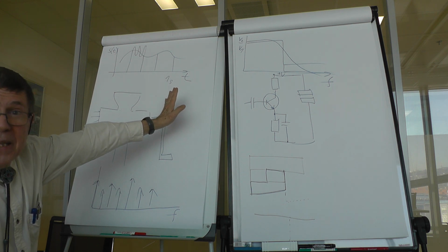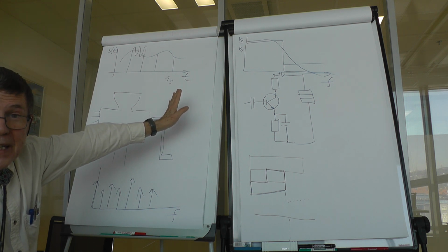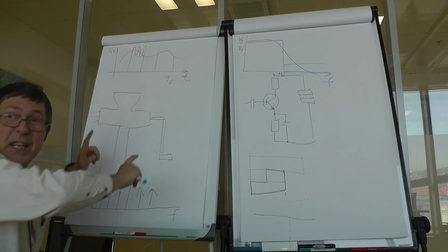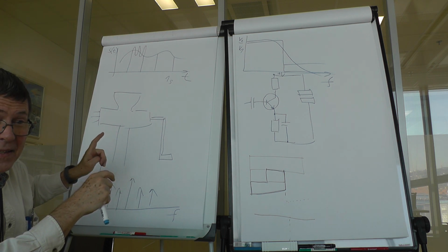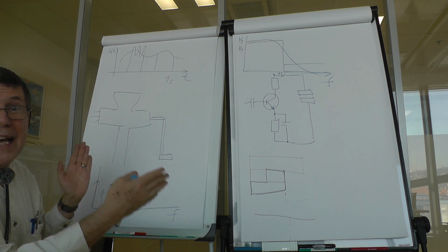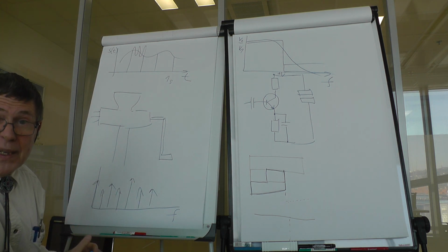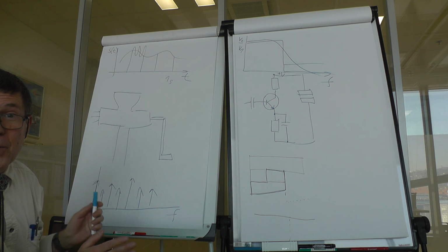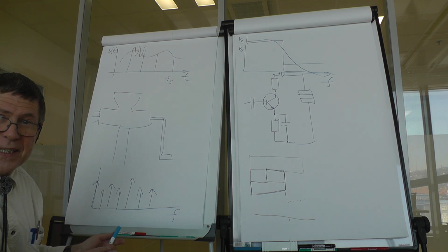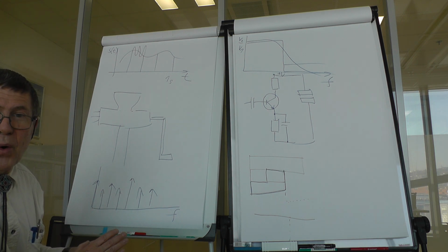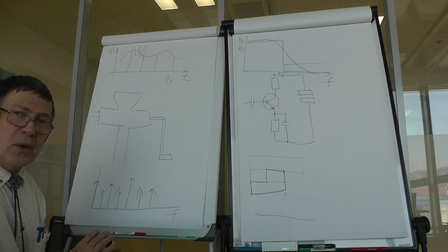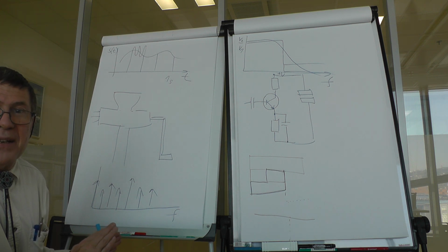It is only reliable in the case that you have really sampled a periodic signal so that the sampling time matches with the time of one period or 7 periods of that signal. Otherwise, you get an additional error which could be up to 100%. So yes, if you have a frequency component produced like that in your calculations, you can be sure that there is not more than 2 times the amount you have obtained. But you are not sure that there is any frequency component there.